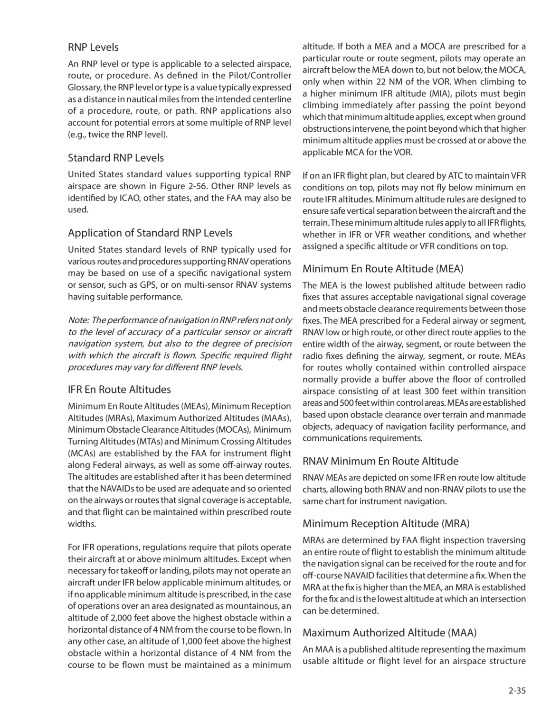Application of standard RNP levels. United States standard levels of RNP typically used for various routes and procedures supporting RNP operations may be based on use of a specific navigational system or sensor, such as GPS, or on multi-sensor RNP systems having suitable performance. Note: the performance of navigation in RNP refers not only to the level of accuracy of a particular sensor or aircraft navigation system, but also to the degree of precision with which the aircraft is flown. Specific required flight procedures may vary for different RNP levels.